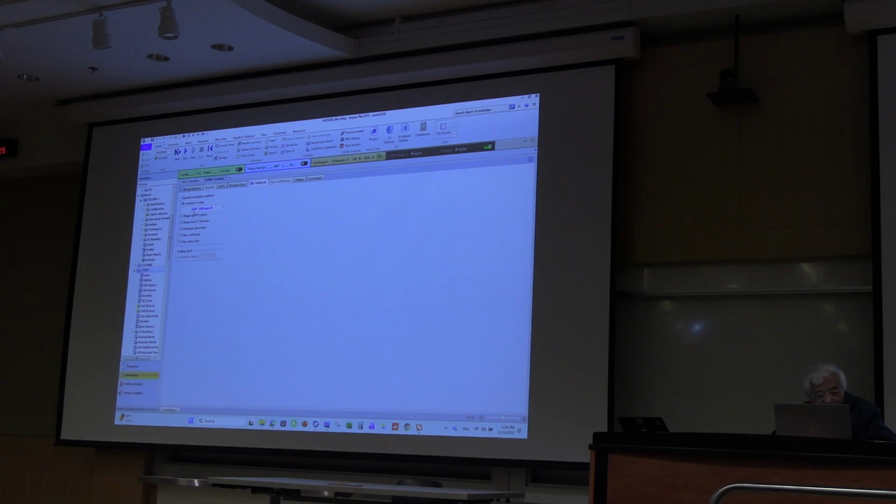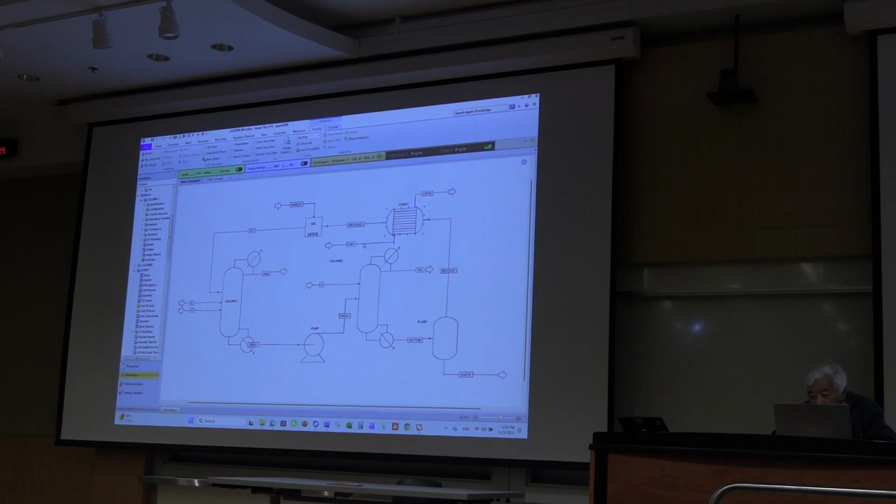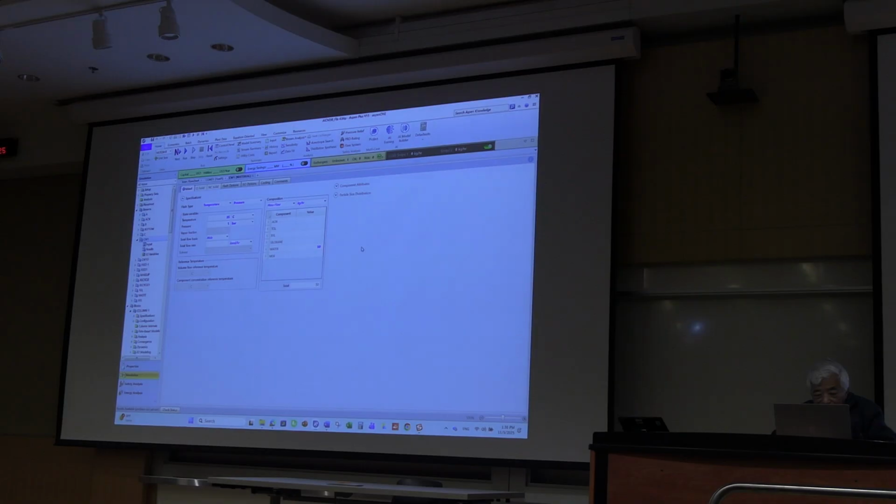You see that heuristic. Set the cooling water flow rate initially, arbitrary number 50. Cooling water goes from 35 to 45. You want to minimize the cooling water flow rate, fully condense the vapor stream.